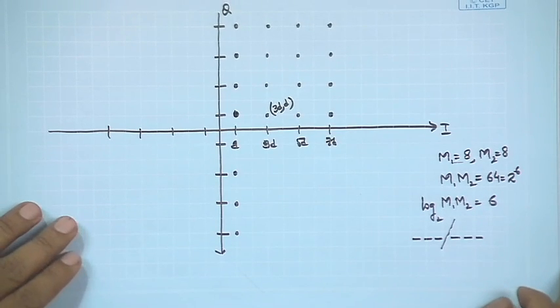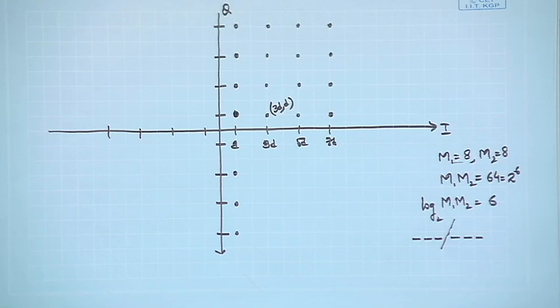Now, an important question here could be whether the gray coding that we had discussed earlier would still be applicable in this case. As I had mentioned, in the case of phase shift keying, you could still do gray coding by allocating the bits in a pattern where the neighboring 2 constellation points differ in at most 1 bit location. The same thing can be done in this particular case as well.